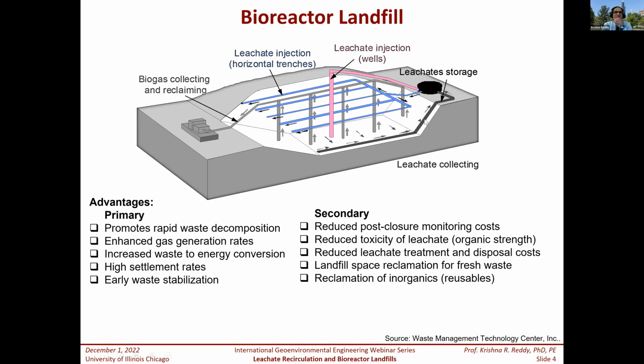But instead of doing that, in the bioreactor landfill concept, you collect the leachate and store it if necessary at the site, and then inject it in a controlled manner into the waste, using either a series of vertical wells, or you could have horizontal wells. So basically, you are trying to inject the collected leachate from the bottom into the waste.